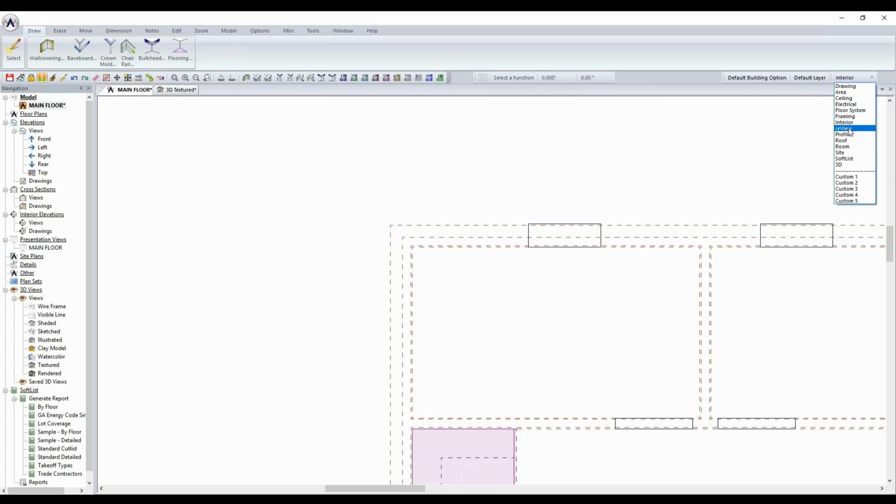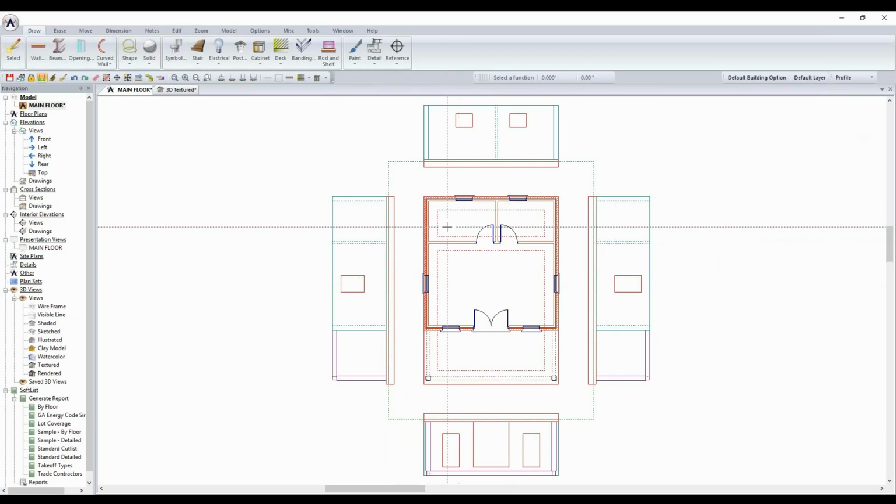Cable jacks, that sort of stuff. They can position them, and then you can bring them back in here as an overlay and then add them into your drawing. Okay. Profile mode basically is a diagnostics mode. It lays the walls down so you can see just how they look if they were to literally just fall outward. And you can see our slab, and then our wall goes up from there to the top of the wall. And it gives you a good idea whether your openings are aligned straight across on the tops and so on.